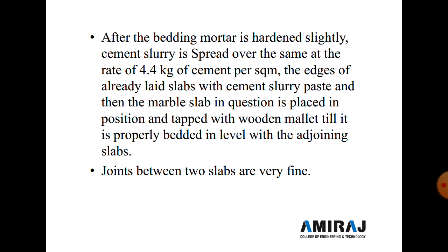already laid slab are also coated with cement slurry, and then the marble slab is placed in position and tapped with a wooden mallet and tilted, properly bedded in level with the adjoining slab, and the joints between the two slabs are very fine, so they are filled up with white cement, and after filling the white cement it is cured for 7 days,